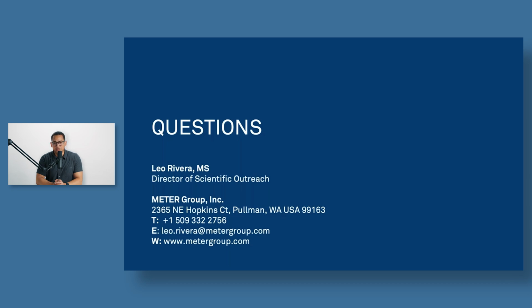So what I would recommend doing is actually using something that can measure your matric potential, and then combining that with a sensor that can measure your electrical conductivity. So using a soil moisture sensor that can measure electrical conductivity, because from there, you can actually use models to get your pore water EC, but there are also models that you can use that EC measurement to get your saturated extract EC.